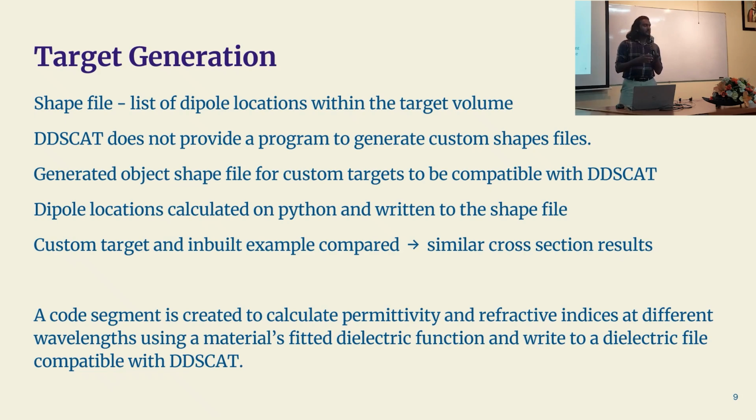With the single particle, I was able to use Mie theory for my calculations. Then, when I needed to simulate multiple particles, I had to use the discrete dipole approximation. So that particle distribution I generated in Python using a code that I created. It's a matter of generating points in a given region that you specify, and that information was used in my scattering calculation software. Also, the material's permittivity information is specified here.